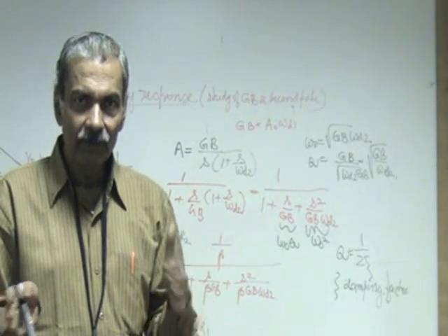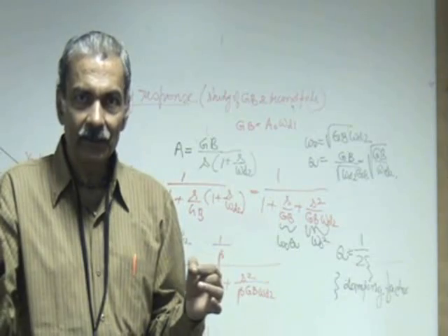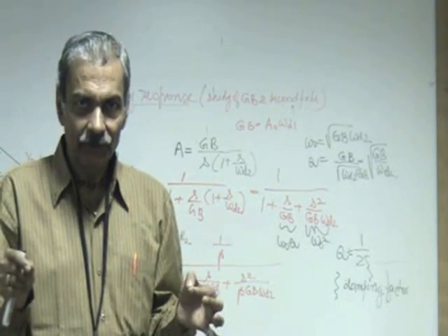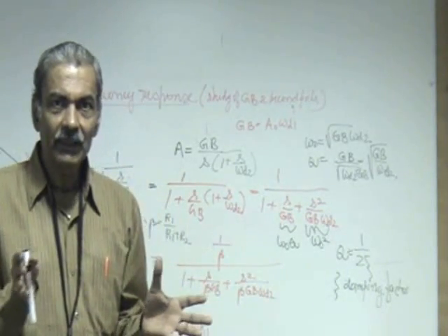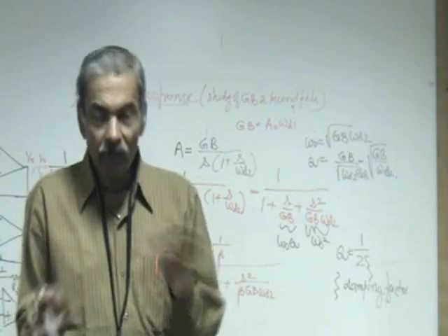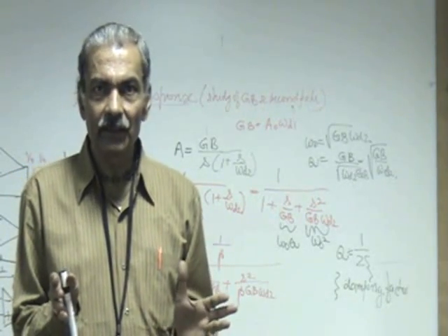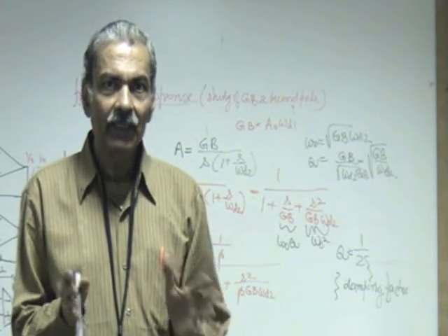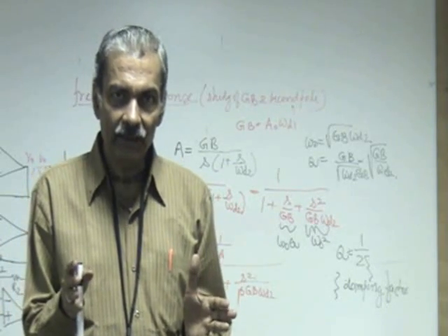If Q is 10, there will be 10 such peakings in the ringing that follows a step input. And that is one way of quickly determining whether the system is stable or not. We do not want this ringing to continue whenever there is a sudden change in input. That will force us to wait for a long time for the system to come to steady state.